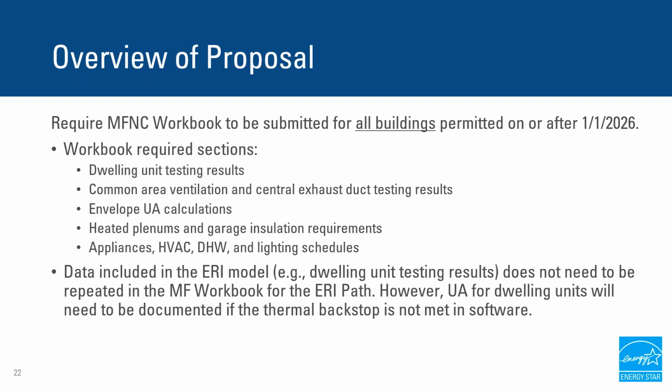However, data that's already included in the ERI model, so all of the dwelling unit testing results and the dwelling unit envelope data and the dwelling unit appliances, et cetera, does not need to be repeated in the multifamily workbook for the ERI path. That said, if you are not meeting the overall UA for dwelling units within the software and you are choosing to use the building level UA, then you would need to document the dwelling unit UA compliance in the workbook.